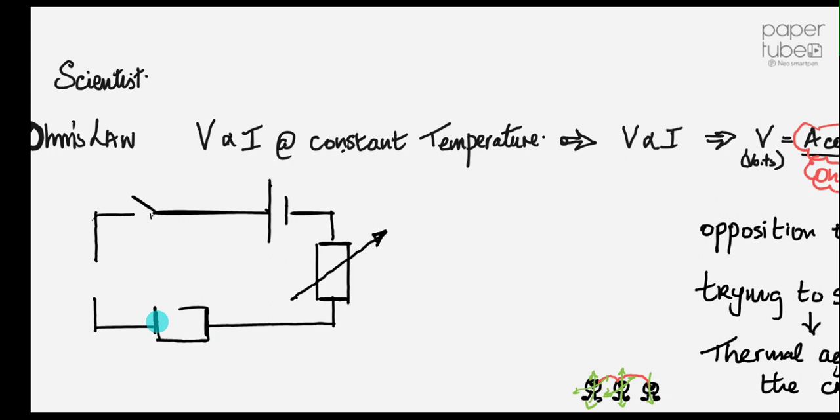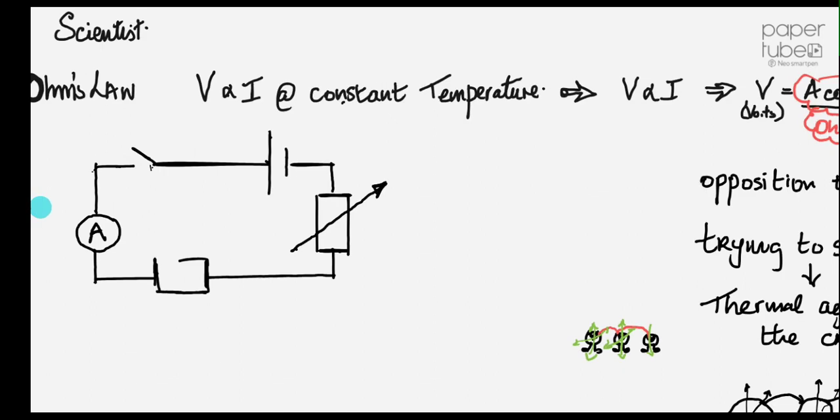I just have to put the two devices in to measure current, and remember Agatha the ammeter. Agatha always makes an ass of herself. Well, ammeter, small resistance and in series. I'm going to put in Vince the voltmeter. Remember Vince with the bandy legs? Severe case of rickets. There's Vince. Fair enough. And Vince, the voltmeter, is parallel and has a high resistance.